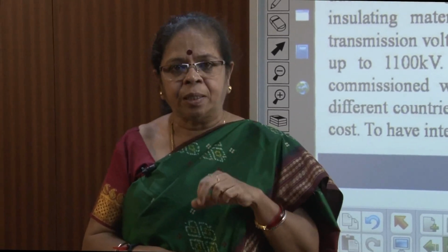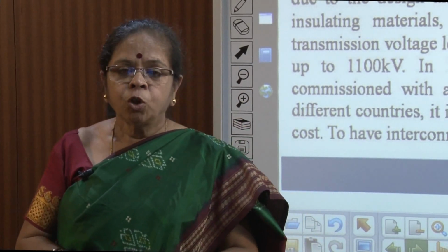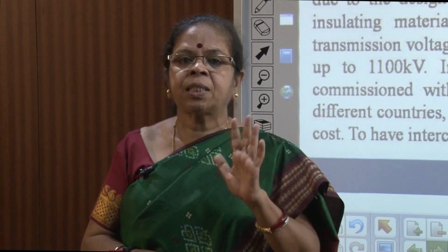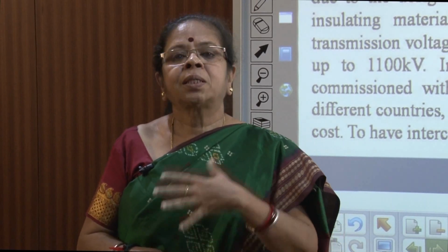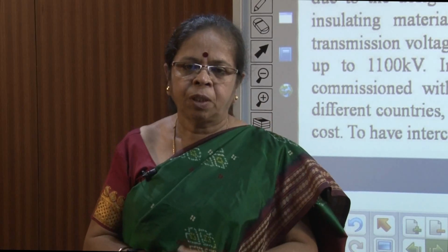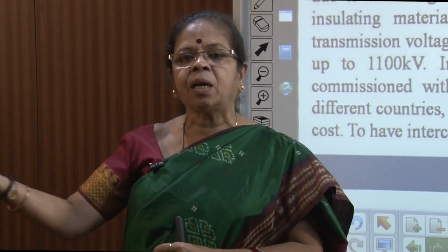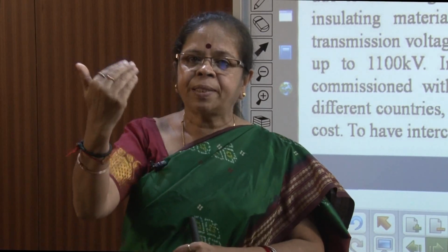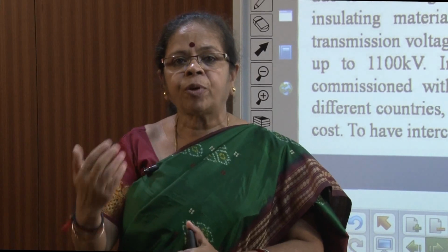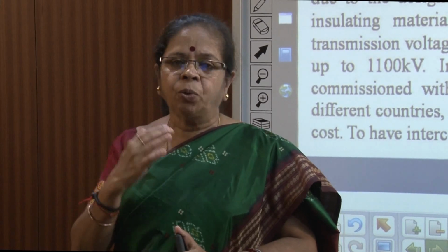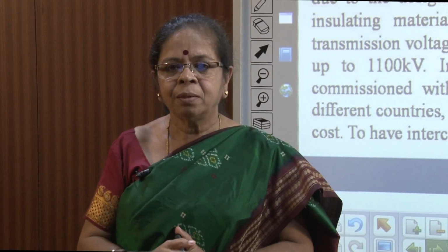So, in a particular country, the voltage level is standardized so that you can have interconnections of products. Throughout the country, every single electrical product designed should operate at the same voltage and the same frequency, the standard voltage and the standard frequency. So, if my equipment requires a different voltage, then at the consumer end I again have to use a transformer and step down what we call the utility voltage. Utility voltage is the voltage you get from the utility. So, I have to step down the utility voltage to my requirements if I want a lower voltage from what I am getting at the utility level.